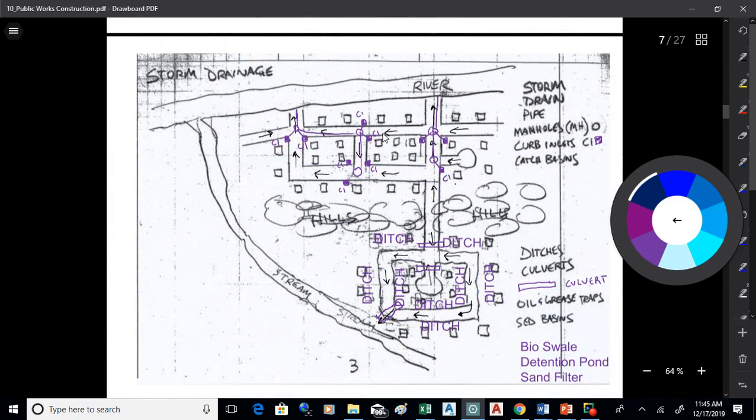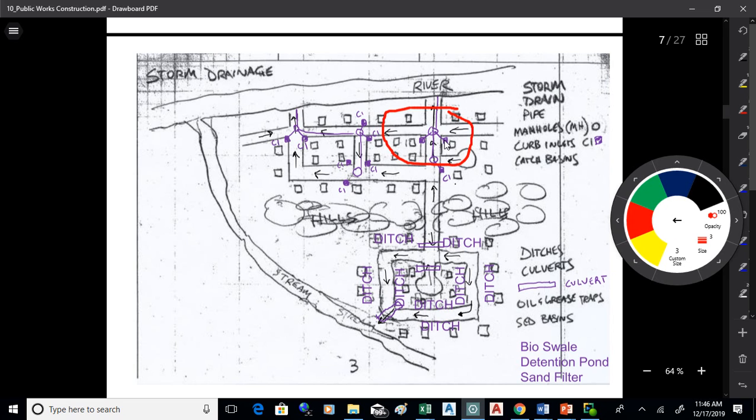So anytime I've got a corner, like this one right up here, I've got the water flowing north and the water flowing west. Well, on this corner right here, the southeast corner, the water's just going to sit there unless I do something about it. So I would put a curb inlet there to pick up the drainage out of the gutter. And I've got curb inlets at a lot of these intersections. That's typically where they're at. But they might also be on a long straight run of road, because you don't want to make the gutter carry the entire flow. Every now and again, you want to put these curb inlets in, or catch basins. So I've got those designated with boxes that are colored in purple.